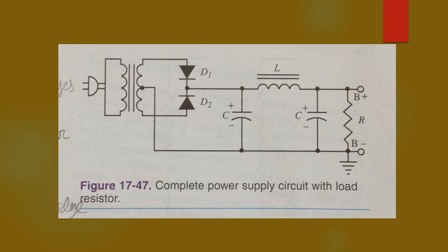For example, assume the terminal voltage of a power supply is 30 volts with no load resistor. No equipment is connected. When the equipment is connected and turned on, the voltage drops to 25 volts. Regulation is 20%. See the previous example under voltage regulation.